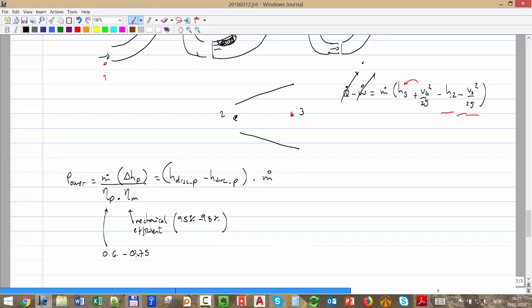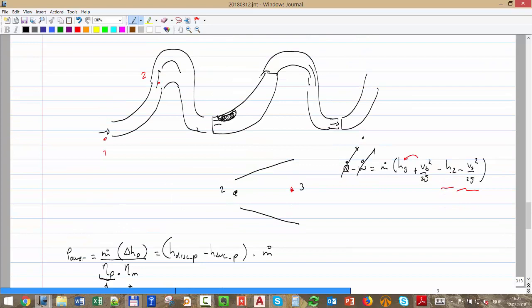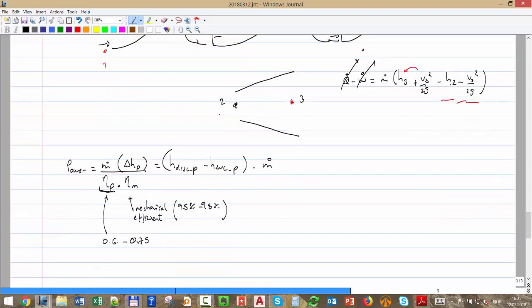Yes. What about the volumetric efficiency? Does the polytropic account for that? No, not really. To avoid confusing you more with the discussion, let's say that it's included here, okay? But in reality, like Juan Manuel said, you have some recirculation. Some fluid goes on the outside of the rotor and goes to the intake, because you have a pressure difference, but that we are neglecting. It's more important for pumps, okay? But for now, let's neglect that part.